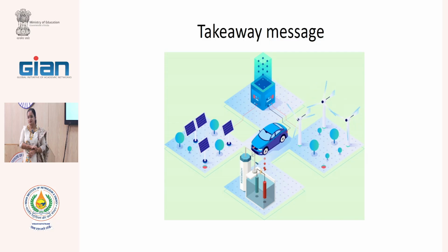For a fuel cell right now, with a membrane size of 5 square centimeters that I have manufactured, it costs me somewhere around 80,000. Or 18,000? Yes. So it is a kind of composite for you? No, otherwise it's a simple PEM with the polymer. I'm using a Nafion 212 membrane. Being a mechanical person, I can estimate the external parts and reduce the cost there, but I'm handicapped whenever I reach the chemical part of it, with the membrane and all.